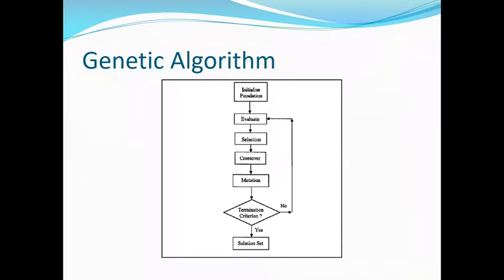This flowchart shows the working of genetic algorithm. Firstly, initial populations are selected on a random basis, but in this work, the initial population has been defined by the search space based on the gain. That is, the individuals are selected where the gain is between the maximum and the minimum gain of the input and the output signal of the power amplifier. Based on this, the error tends to reduce a lot.